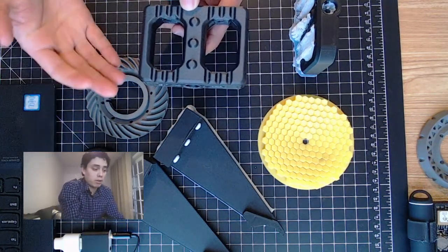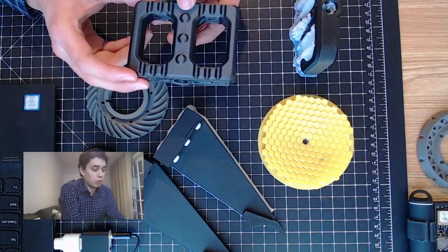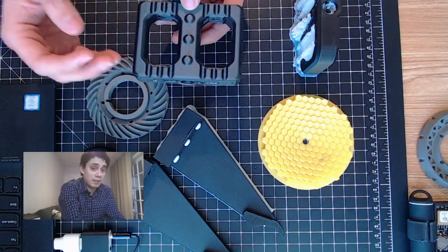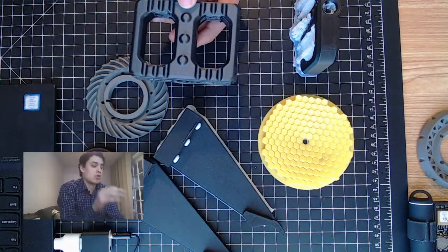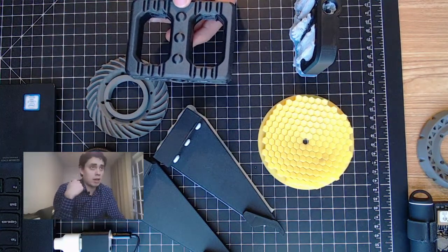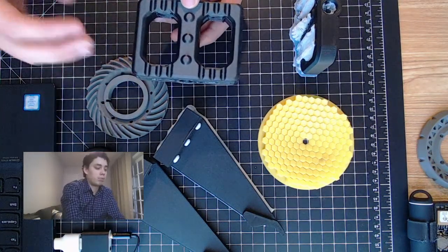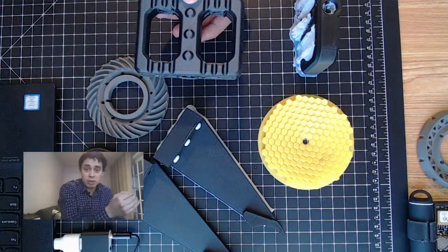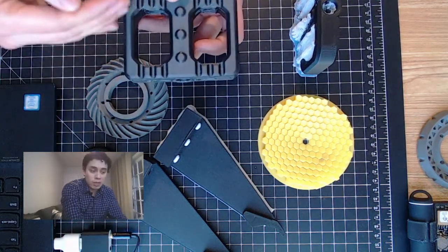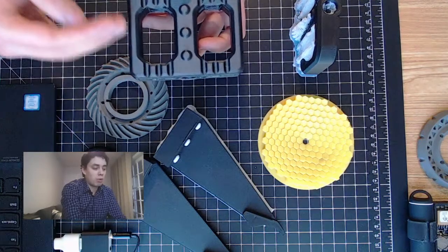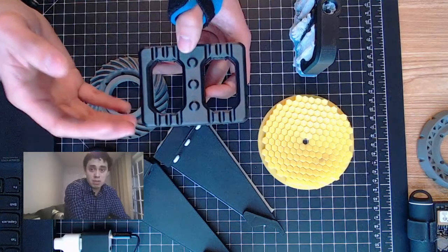That's just a natural part of the process of 3D printing. For any printing process, you will have to keep these types of considerations in mind. Why? Because all printers, no matter which system you're using, whether it's FDM, laser, or powder, all start off from that very first consideration, which is layers. You're splitting an object into layers, and those layers in turn create micro steps within that part that can affect both the performance and the look and feel of the part.